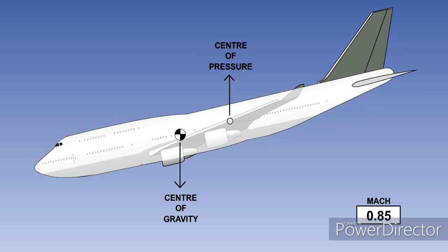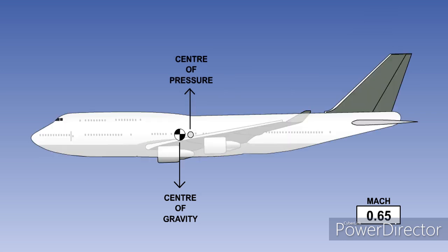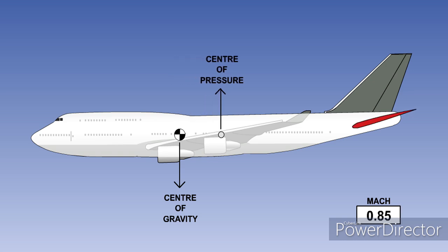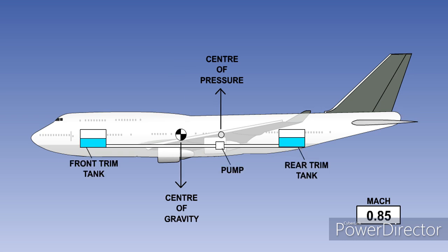Such a system is known as Mach trim, and is designed so that it will operate whether or not the autopilot or some other method of automatic flight control is engaged. The system senses speed increases above a datum Mach number, approximately Mach 0.65, but this does vary with aircraft type, and through a servo system produces the appropriate movement of the horizontal stabilizer, or a fuel transfer to maintain the trim flight position.